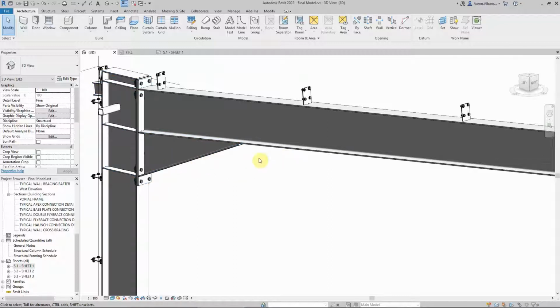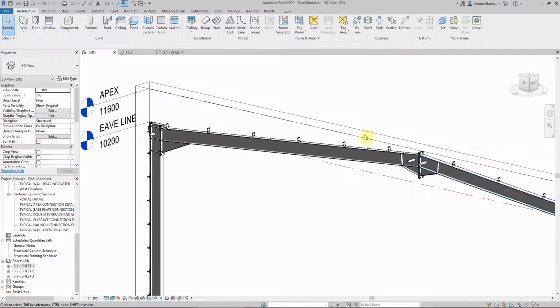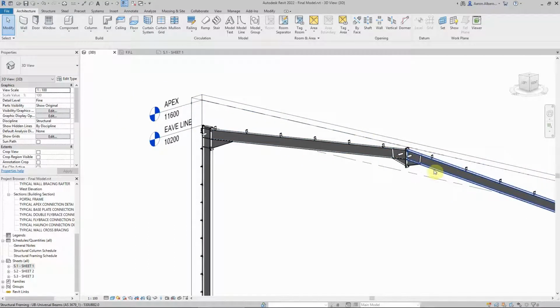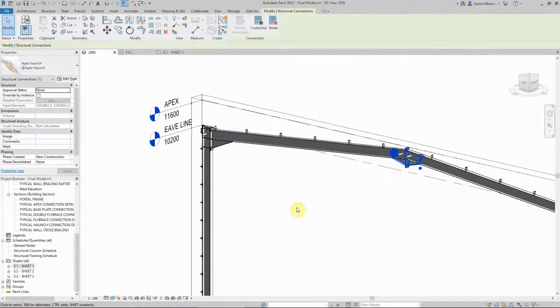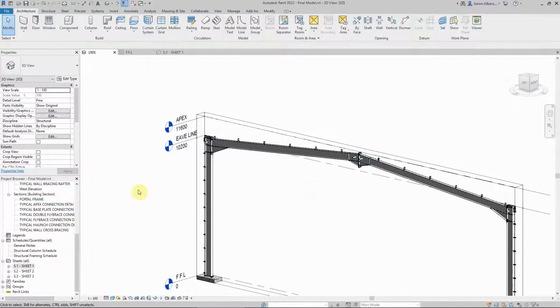We'll call it a haunch. Why do I have to have one of those in the center? The software can draw exactly these two rafters for you, the two beams, without that haunch. I can just get rid of that altogether. It's your job to give the software the right instructions, and we need to understand what the right instructions are. Okay?